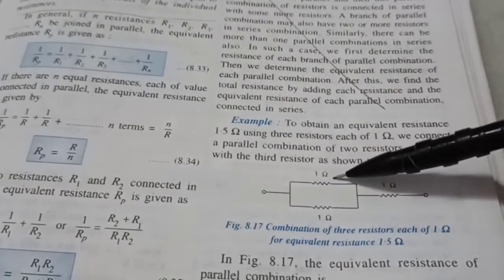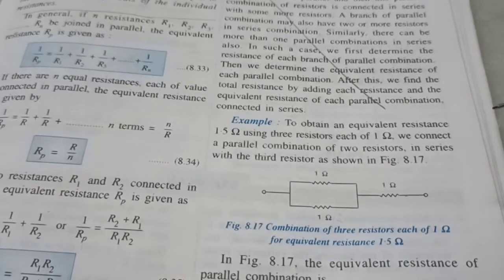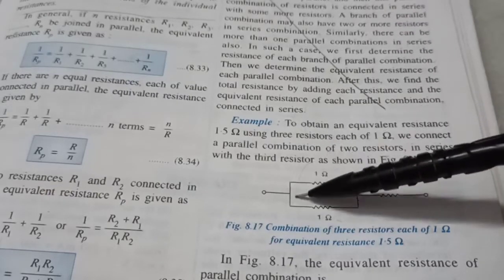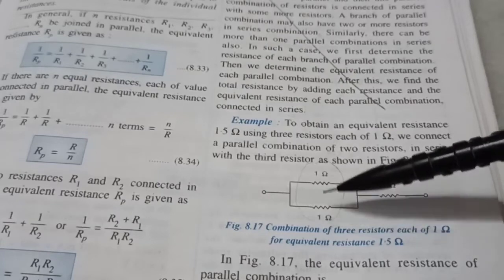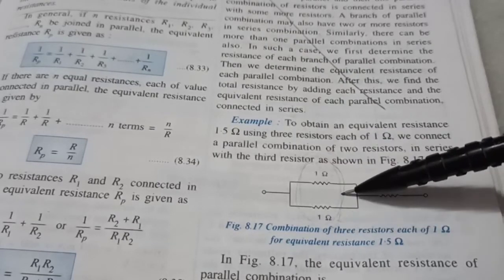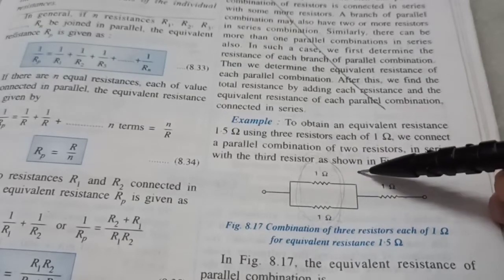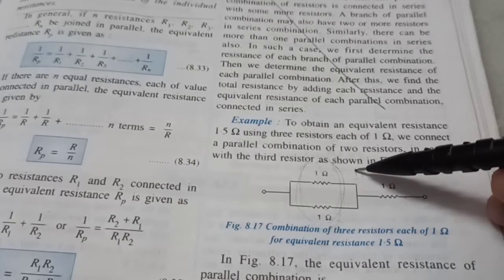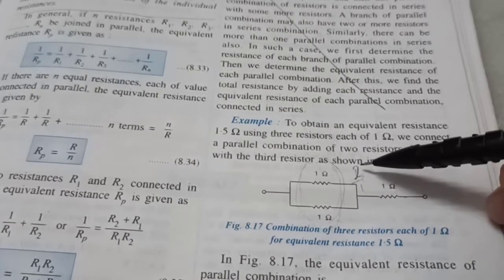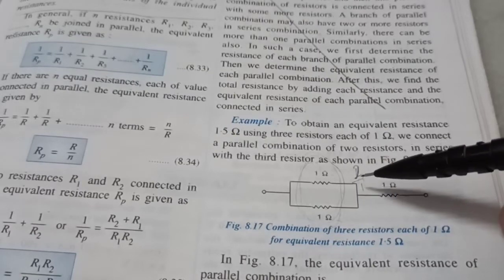But what if you are given an example in which you've got two of them in parallel and then one of them in series? We'll be doing many numericals of this type, which is quite fun and very important from exam point of view. So first we'll calculate this. 1 upon 1 plus 1 upon 1 is 1 plus 1, that's 2. So this total is 2 ohms. Even after reciprocating it, no, so that's a big mistake. So 1 upon 1 plus 1 upon 1 is 2, but that is the answer of 1 upon RP.